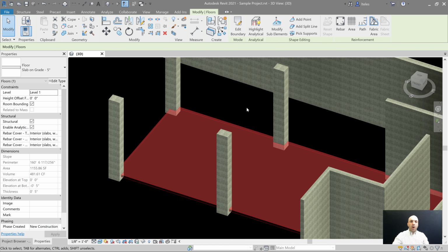So always take things in stages. We have set up our model so that Revit understands what we're trying to do with our column attachments, even though columns get physically built before floors do. But floors are very important for Revit, so we're using floors to communicate with columns. After we've done that, now we can incorporate construction practice, what actually goes in first, which is our columns.